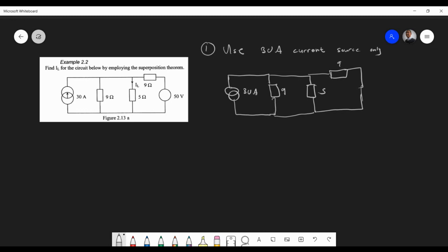So what do we have to do now? Yes, we have to reduce the circuit. And so we're going to find the current in the 5 ohm resistor now using a few tricks. The first thing we do is say those two are parallel to each other, if you agree with me. Of course, we're looking this way in. I think we can do that. That's the first step I would do.